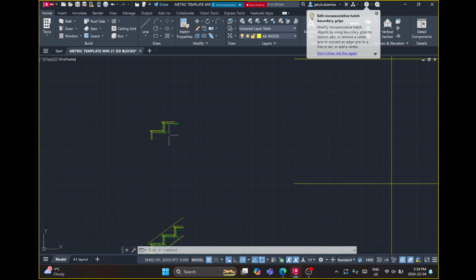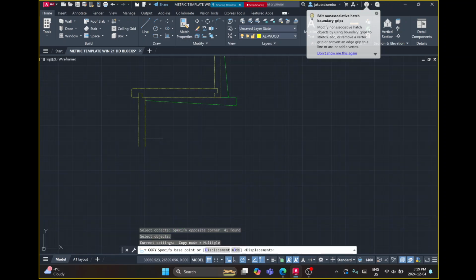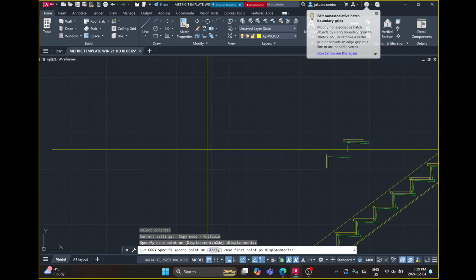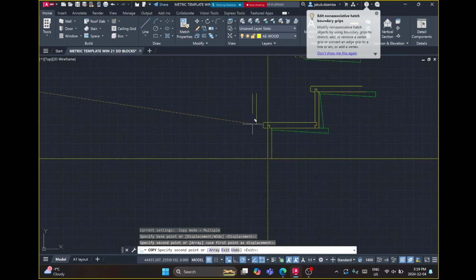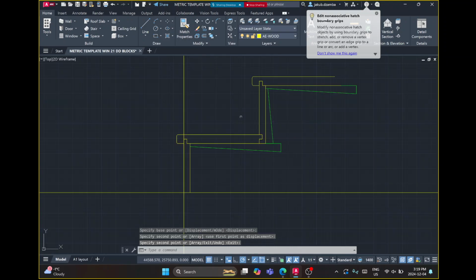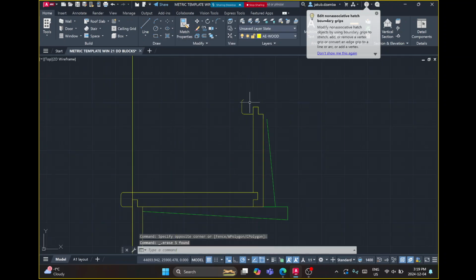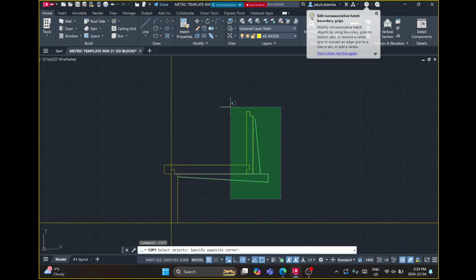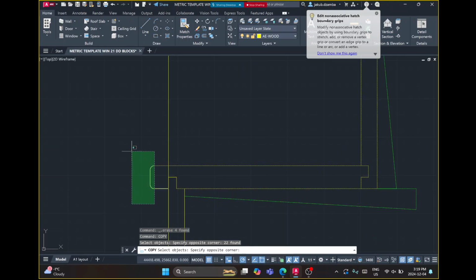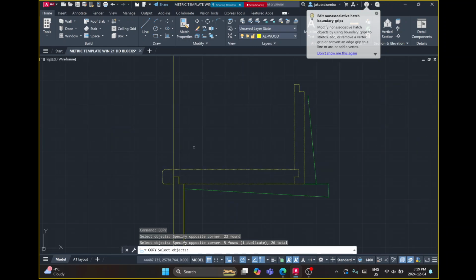So I think we can try to build this second stair. So I'm going to copy what I have here and start it here. And now I need to set myself up so I can copy this the same every time. So I'm going to delete this wedge. In fact, I'm going to delete this too, I think. And I'm going to copy all of this and this. And I'll make this top corner my base point.